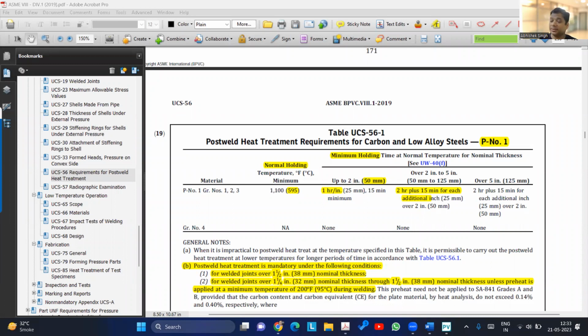Dual certification means you can have a material with a specification which is qualifying for 2 different specifications. Like it is getting qualified for 304 also, 304L also. Both the requirements are getting met, so you can provide a dual certificate. You can use it as either 304 or 304L or 316, whatever the certification has been given. No design change, just consider that material. It will give flexibility for selection. Design wise, there is no change.